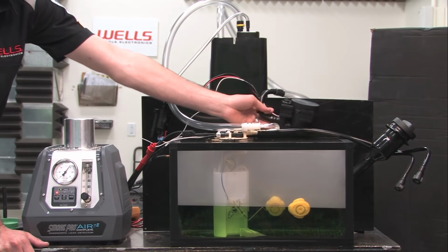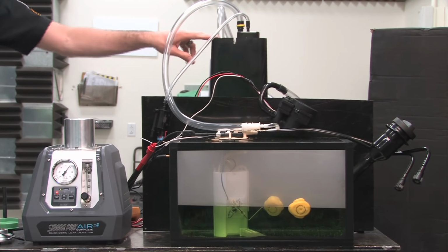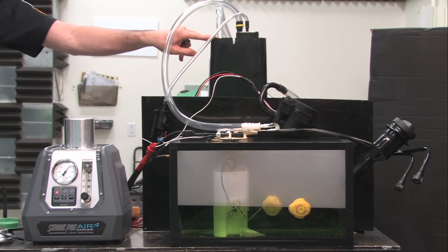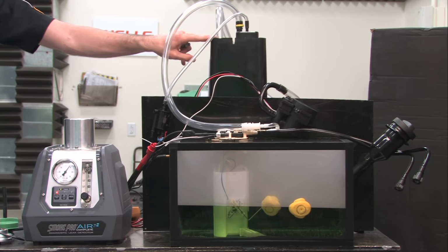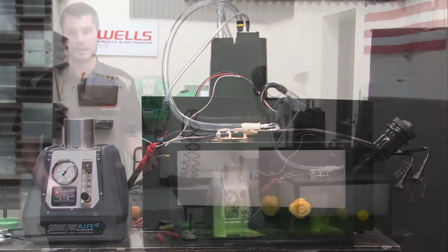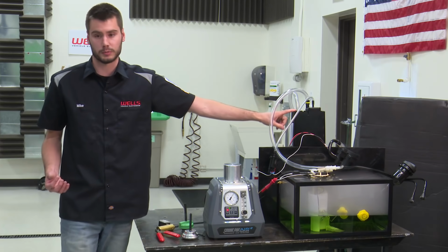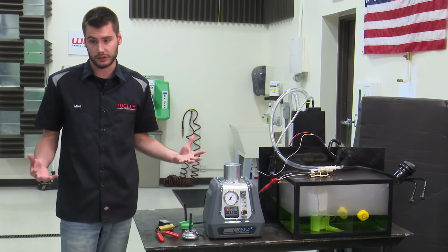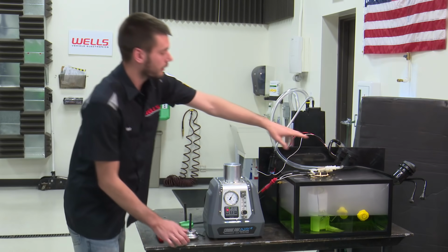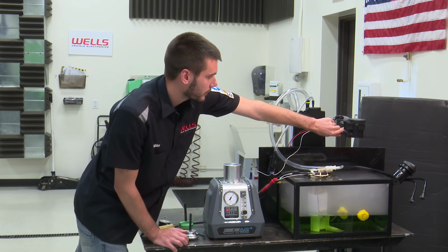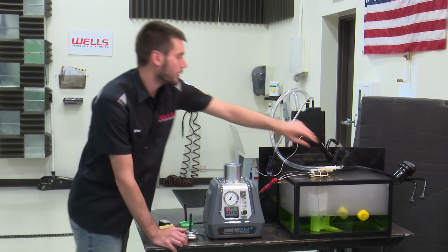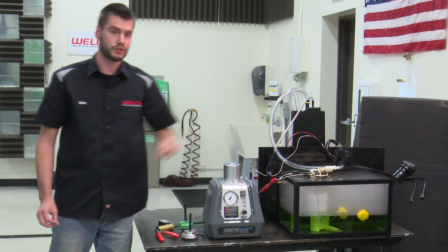Now the reason why there's smoke coming out of it is because the charcoal inside of here is not actually absorbing the molecules of the smoke. Because how good would a smoke test do on a vehicle if the charcoal canister absorbed all your smoke before it would even get up to the purge solenoid? So our vent solenoid is going to show the smoke coming out of it. It is venting it, but again, this would not be fuel vapors. This would just be fresh air.